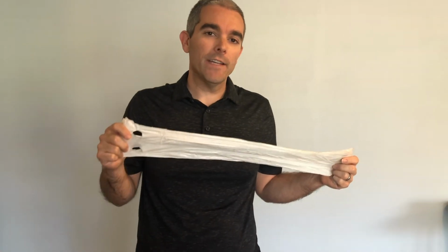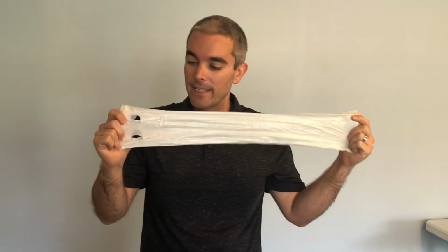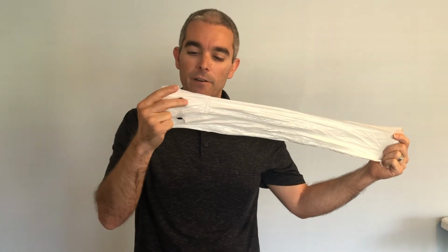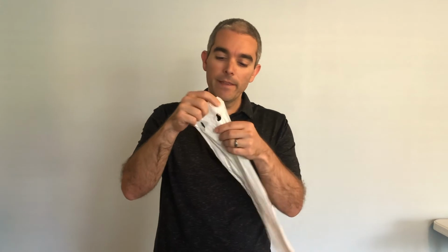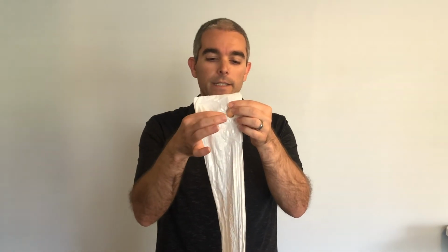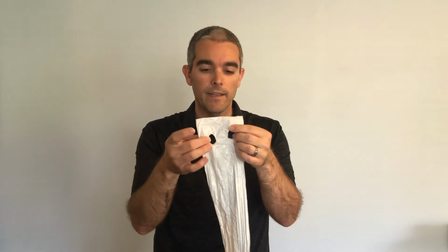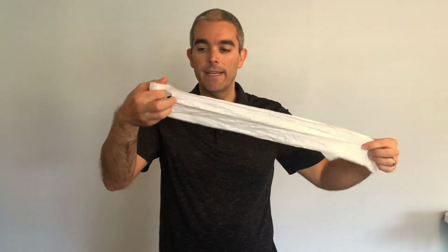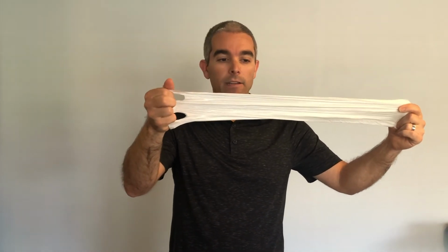Now we're going to look at fracture. A lot of you probably saw this thing and said immediately it was going to fail over here at the connection, right? And you probably think this because look, right at the bolted connection, we have less material resisting the force. And so when we pull on it, we're expecting failure to occur probably at this cross section.